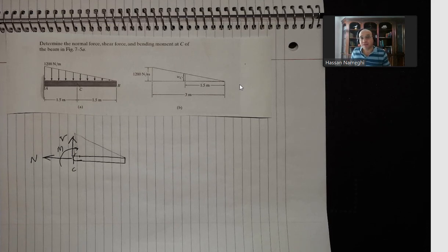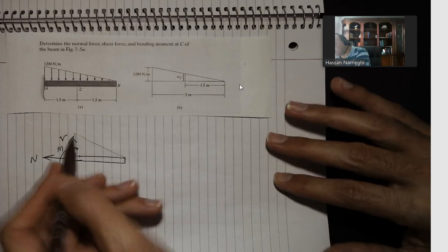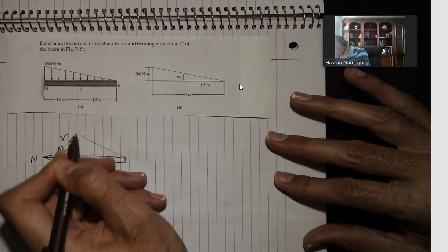It will be A, exactly, because you have the maximum moment there. All those little forces add up and they become too much there. Now, in this case, I'm looking at point C, and I draw the free body diagram only for the right side. How much would the height be here on the load?